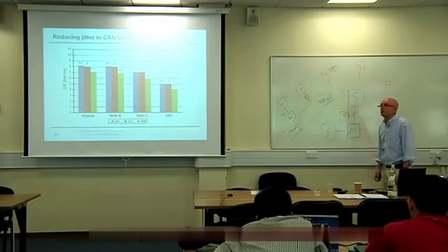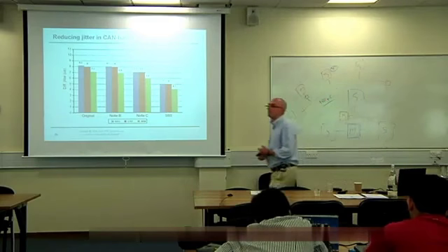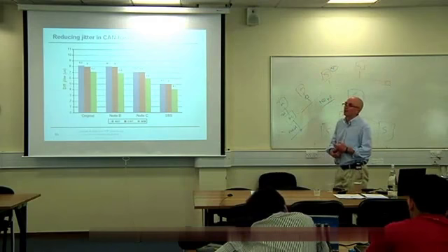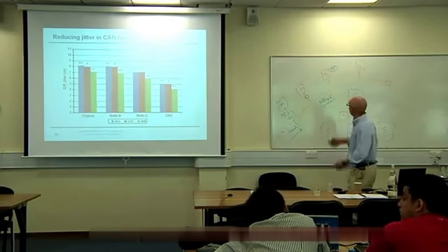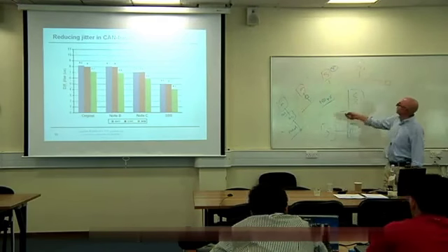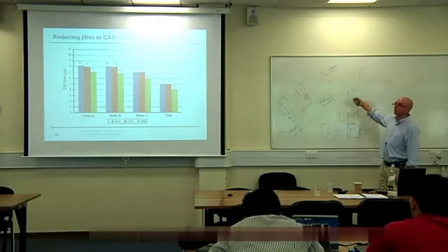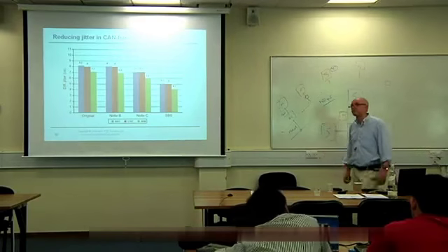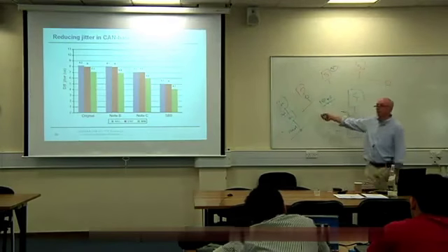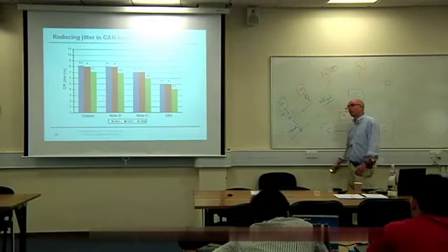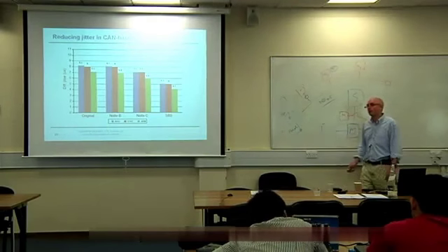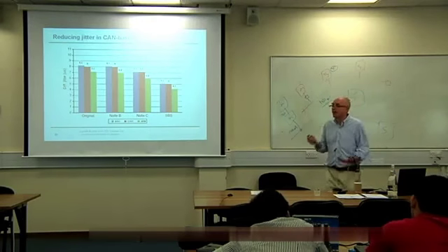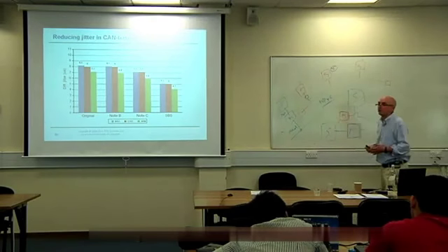these guys. Wasn't the data sent by master? So if it doesn't send the data, what's the easiest way to get the data sent? Would we use another slave? You'd have to, essentially. If you had 3 nodes doing data sampling, control, actuation, we now need 4 nodes. Yep. And this might be an 8-bit microcontroller, because it doesn't have anything to do. So it might be a really very basic microcontroller that's just sending the tick messages. But there isn't another solution, essentially, to that.